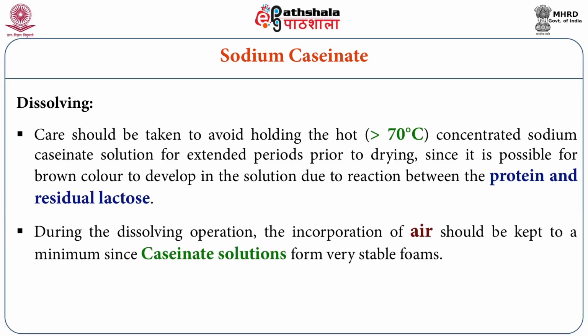During the dissolving operation, the incorporation of air should also be kept at a minimum level, since caseinate solutions form very stable foams. So, care has to be taken not to hold the mixture above 70 degrees Celsius, and during pumping operation care has to be taken to prevent air incorporation in the sodium caseinate slurry, which otherwise leads to problems during drying.